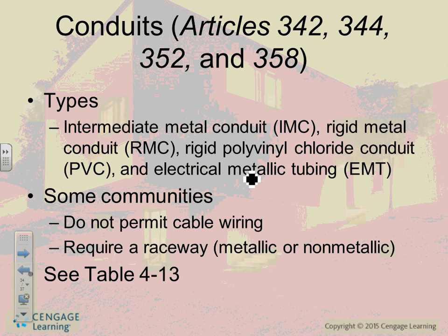Okay, so that's a few rules, guys, about Romex cable, the most common. Any comments, any questions? I'm going to run you through all these articles, guys. Now, remember, rule number 1, Romex cable, MC cable, AC cable. Now, if you're going to go to conduits, guys, your conduit of choice, we just talked about this one, 95% of the time, EMT. You're looking at it right here.